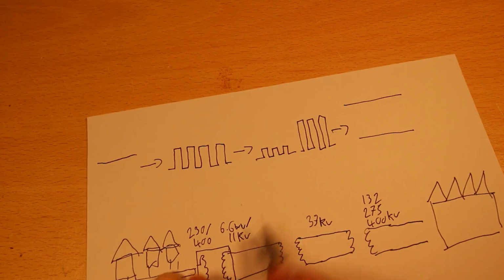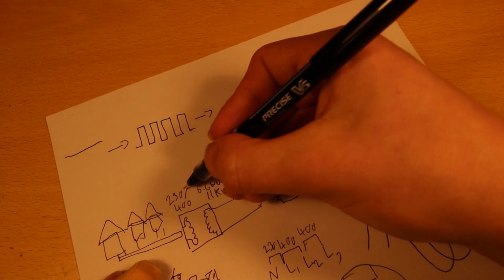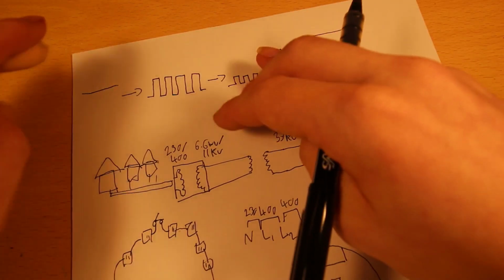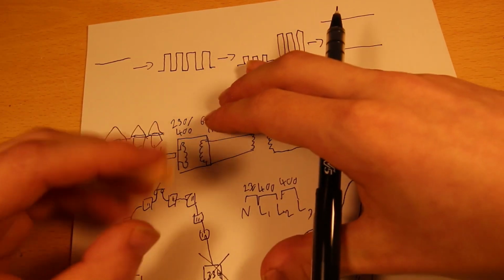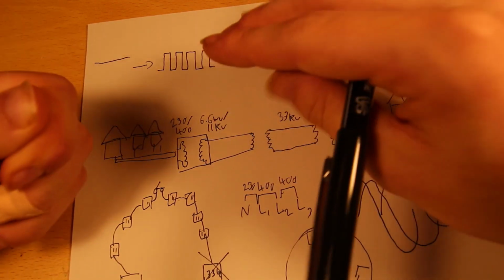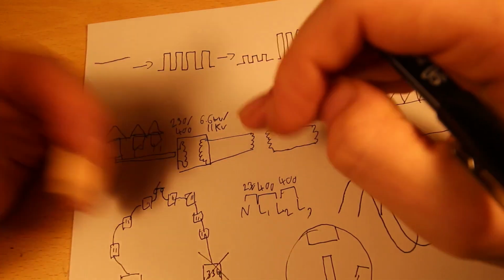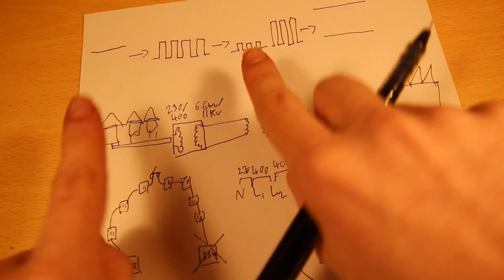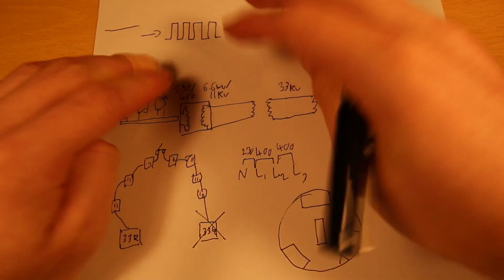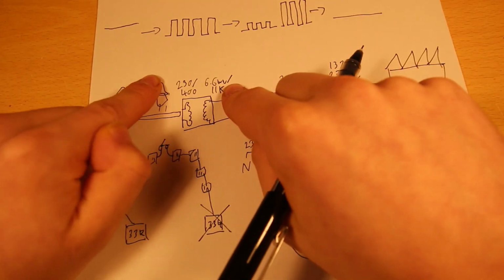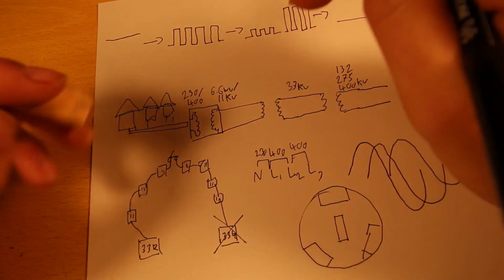And that's what I meant up here when I said there were 2 voltages, and I'd explain why in a second. The smaller one is what's called the phase-to-earth voltage, which is the voltage between the line conductor and the earth. The higher voltage is the phase-to-phase voltage, which is the voltage between the 2 live conductors. So on 11 kV, it's 11,000 volts between the 2 phases, only 6,600 volt between the phase and the earth.